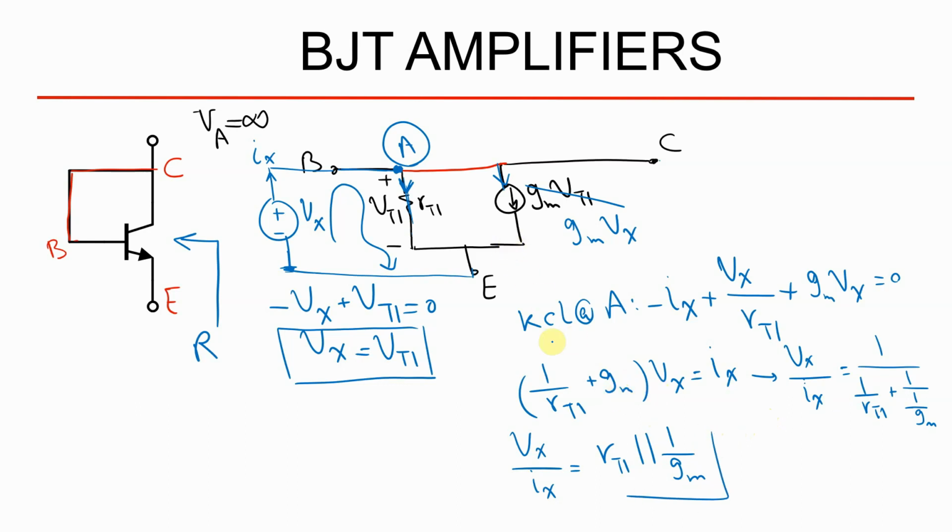If you look closely, you can see this at the beginning actually, because this is r pi, which is completely obvious here. But how about the 1 divided by gm? This is the dependent current source. Depending on what? On its own voltage. So you can simply say that this is equal to a resistor.